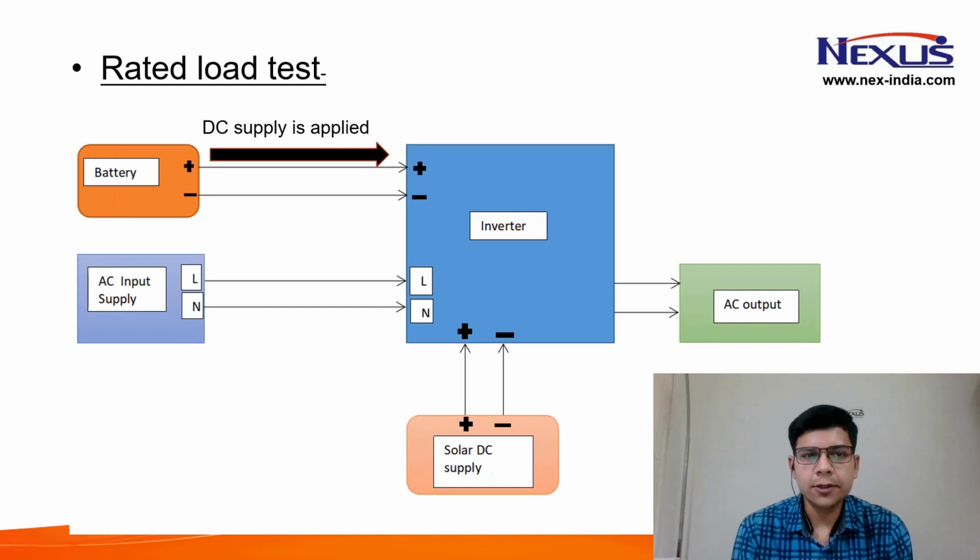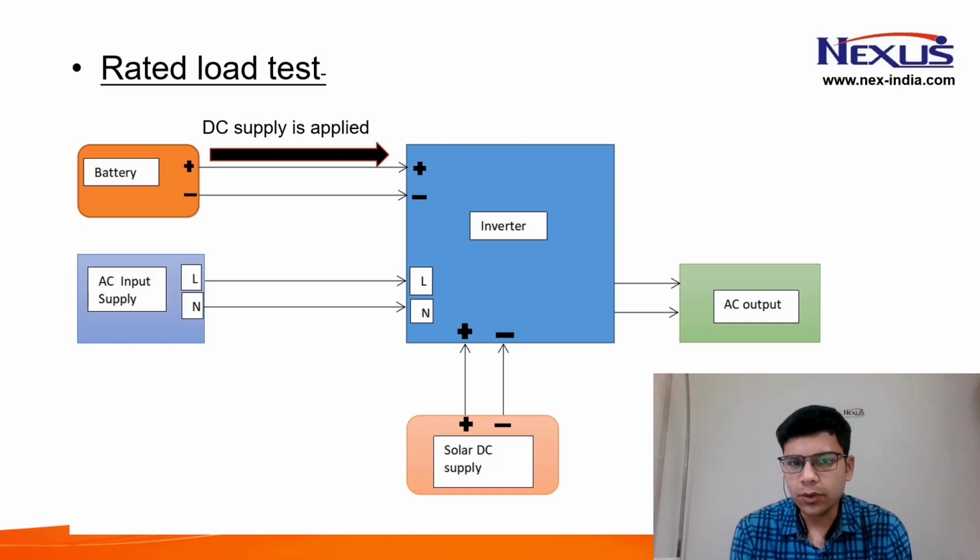Next, the rated load test. As the name suggests, in this test we are going to operate the inverter at rated load, and again we have to measure the output voltage of the inverter as well as the current drawn by the inverter at the rated load.